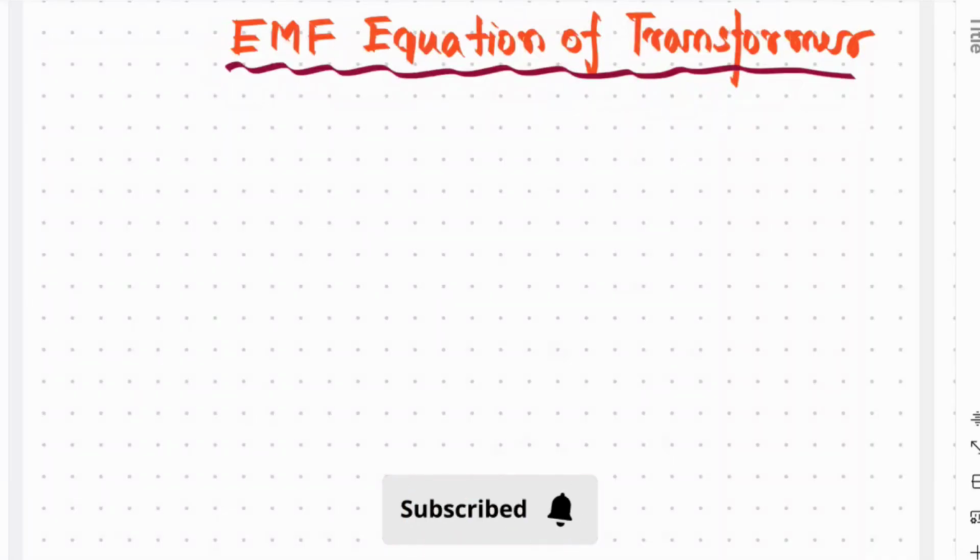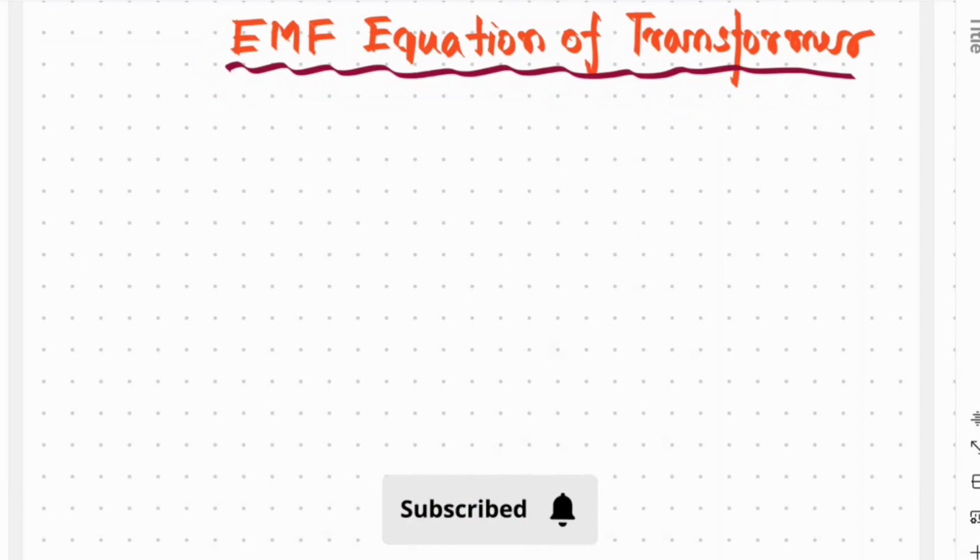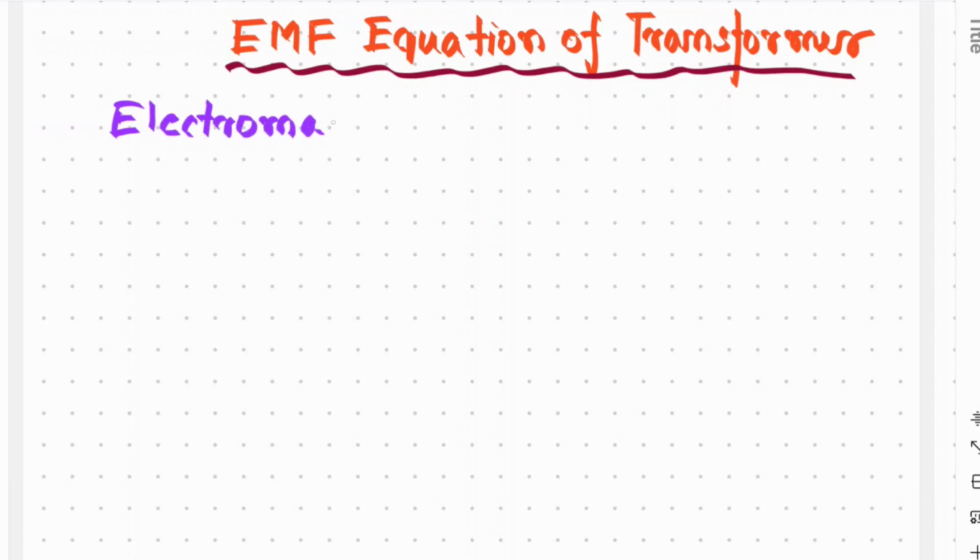In this lecture, we will understand the EMF equation of a transformer. A transformer works on the principle of electromagnetic induction. When alternating current flows in the primary winding, it produces a changing magnetic field, magnetic flux, which produces an EMF or voltage in both the primary and secondary winding.